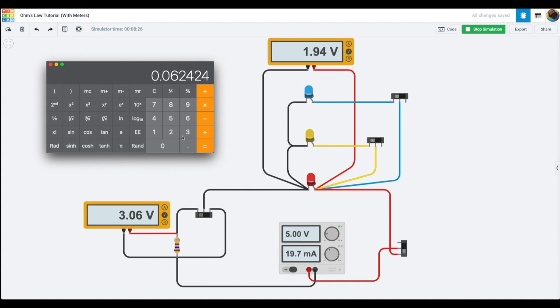Okay. And that's important too, because you can get different sizes of resistors: 1 watt, half watt, quarter watt, and you have to make sure of that. I always go with half watt or 1 watt resistors anyway, because usually that's sufficient. So anyway, that is basically how you determine current through a circuit, and how to determine what size resistors you need for how much current or power you need.